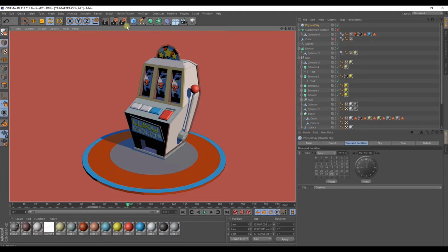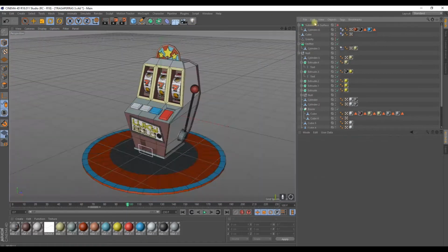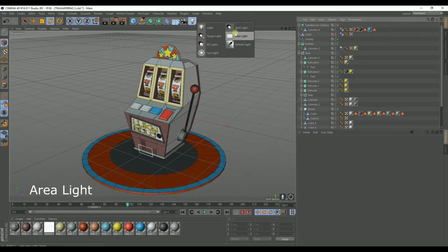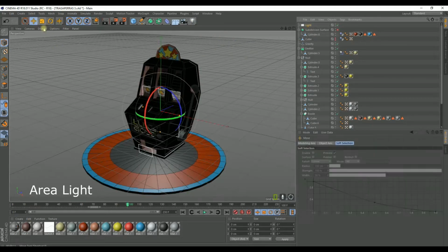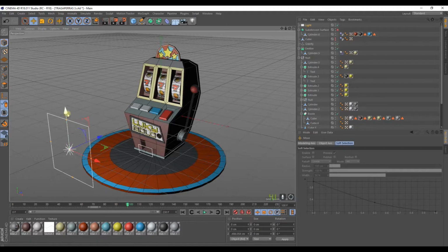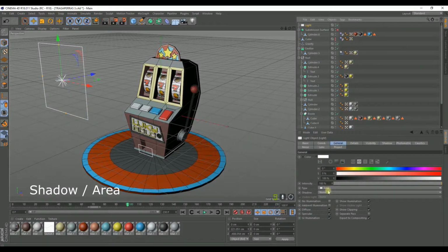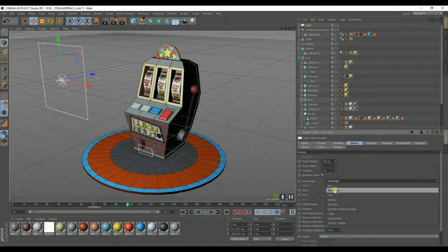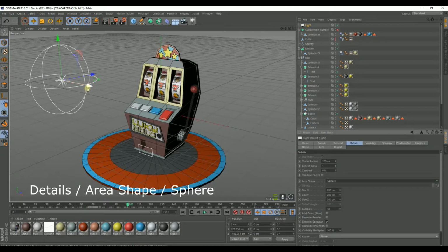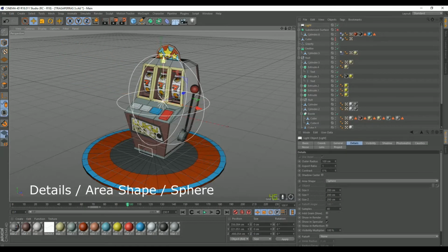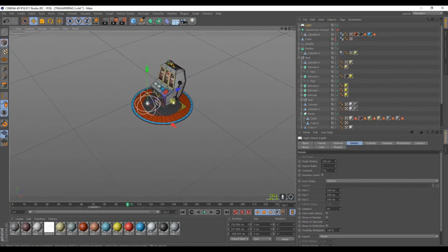All right, so we can see that the light here covers the area below. The shadow. This is because we have to go along playing with the lights. The sky, we can eliminate it, for example. Let's put in a light, an area light. We can move it to around here. We're going to go to light properties. And here we're going to put in an area shadow in this window. We're going to mark sphere. We're going to place it around.